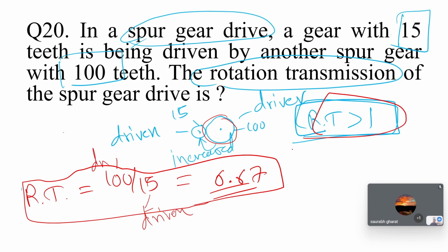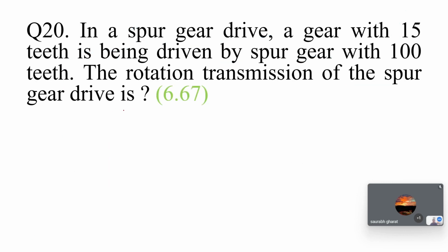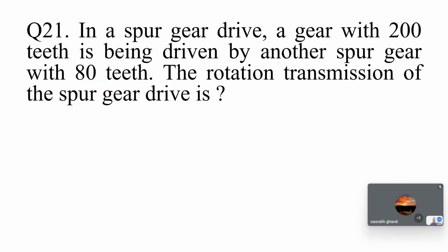And how much more than that? You can get it by this simple formula, dividing your driver by your driven part, and this answer comes to this point. You know it is more than one, but how much more? It is 6.67. This is your answer.